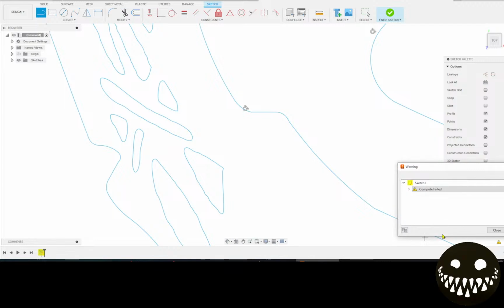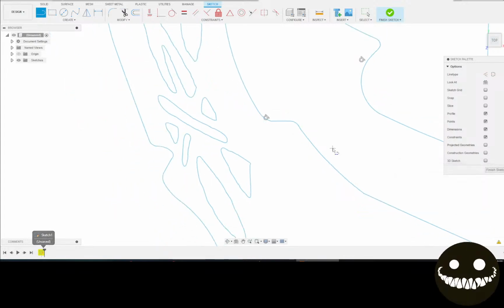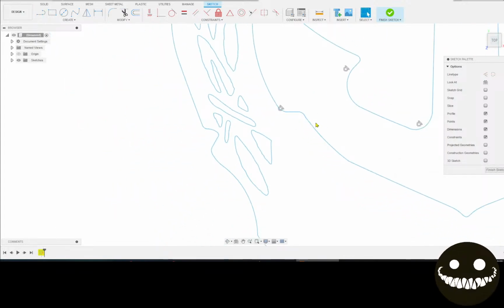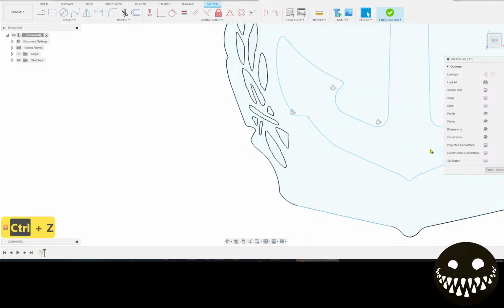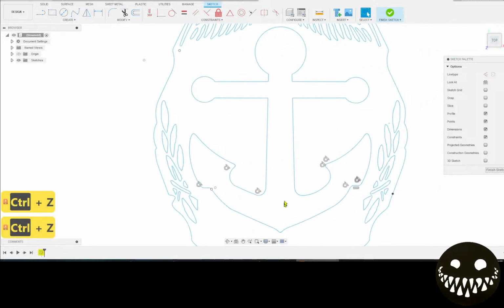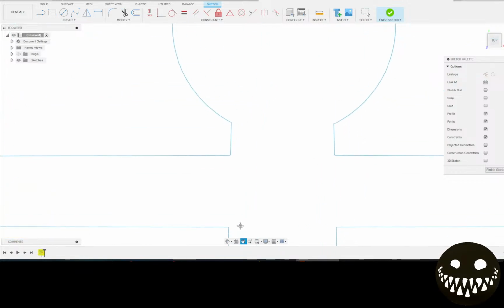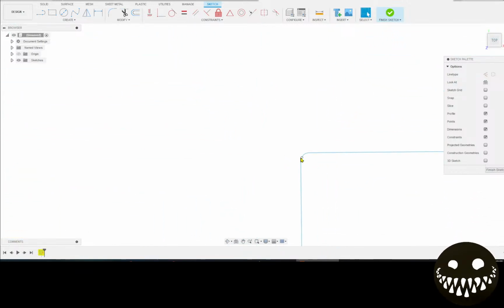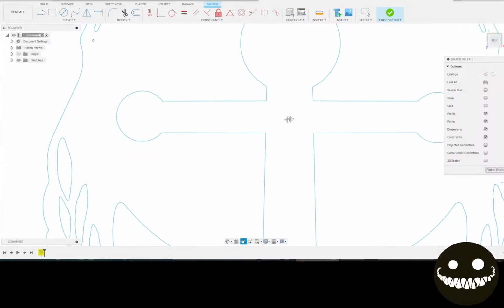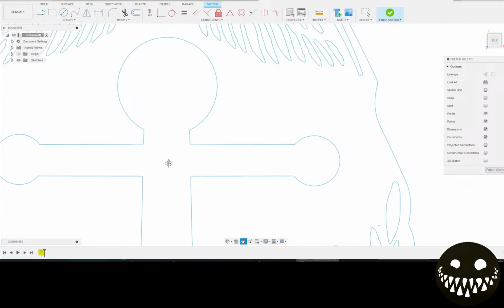And again, we were met with compute failed. Compute failed with no real... The curves do not overlap precisely. Interesting. So, Control R, we're going to just go back to how it was. And then I started probing around, looking to see if these corners were tight. You know, some of these corners are not sharp, and some of these corners are sharp. So it's like a trace to bitmap or something like that generated this.